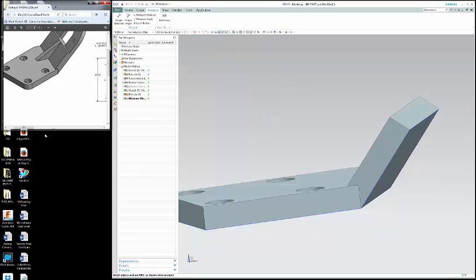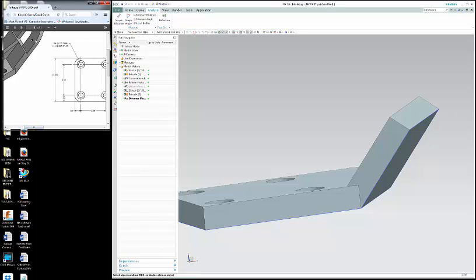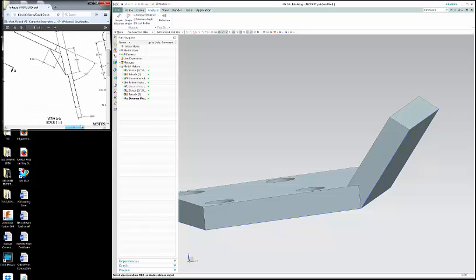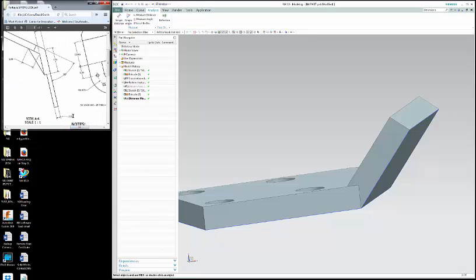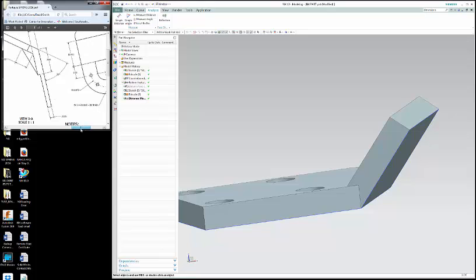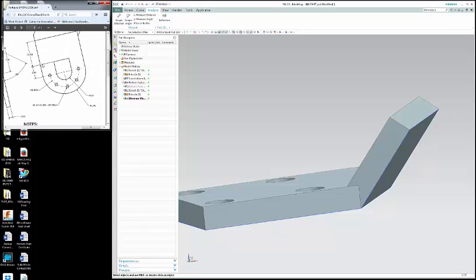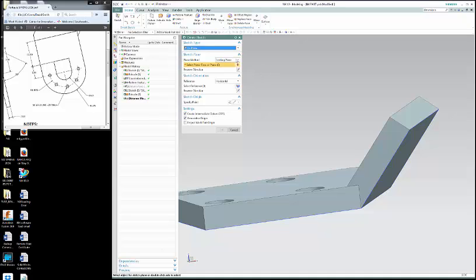Okay. So then what we'd want to do is draw that other shape there. Now that does come from the back, and it's only going to be 0.3125. So we'll draw that shape. Notice it does go up an inch from this edge. The first thing we need to do is get on our sketch plane. So we'll go sketch, on plane, existing plane. Let's go right here.